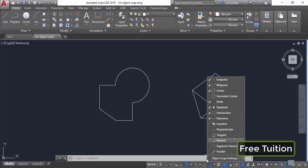So currently the object snap will only recognize the points which have these check marks, and it's always advisable to keep only the required number of check boxes active. Don't make all of these check boxes active, otherwise there will be a conflict of different object snap points. For now we have endpoint, midpoint, center, node, quadrant, intersection, and extension points active, and currently all of these points can be recognized by the object snap.